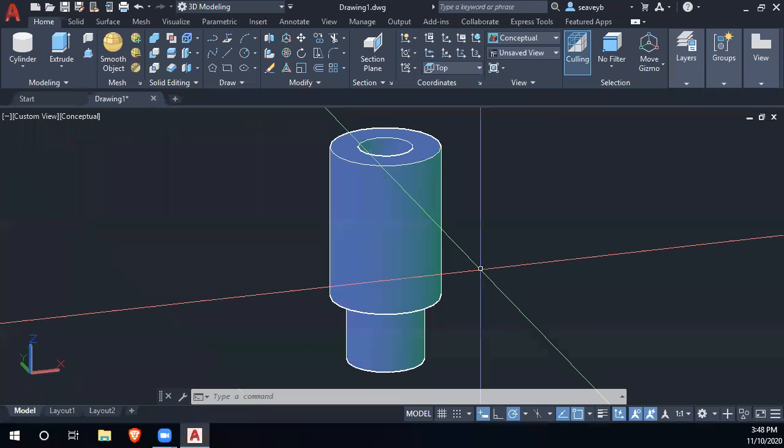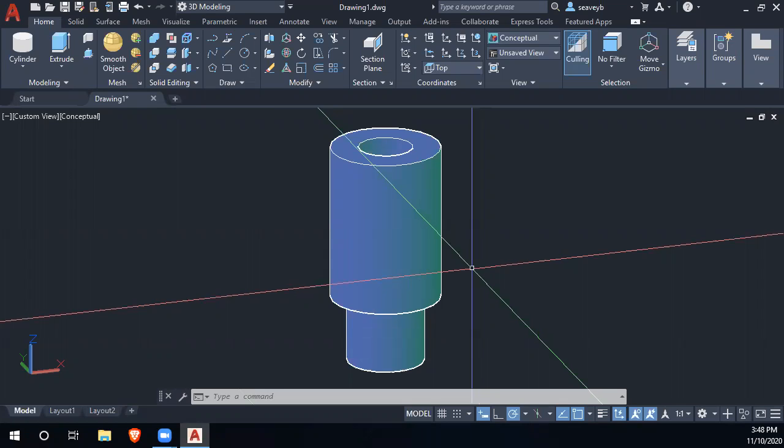On to the next part, the clamp head. You can think of that as a very complicated object, or not, I guess. But in this one, I see a tab on it: the clamping part and then the cylindrical part to it. So I see that as two objects joined together, because we have that solid union tool that could do that. And then we could also punch a hole in it. So let's do that.